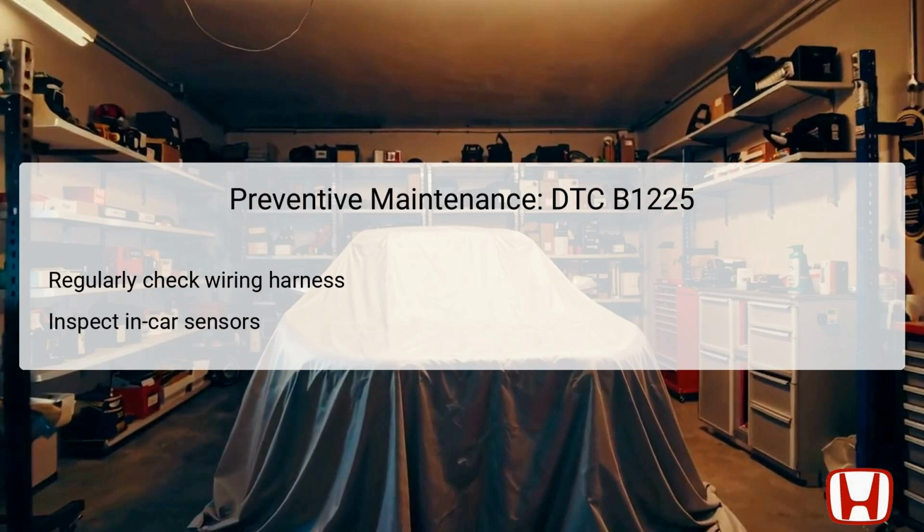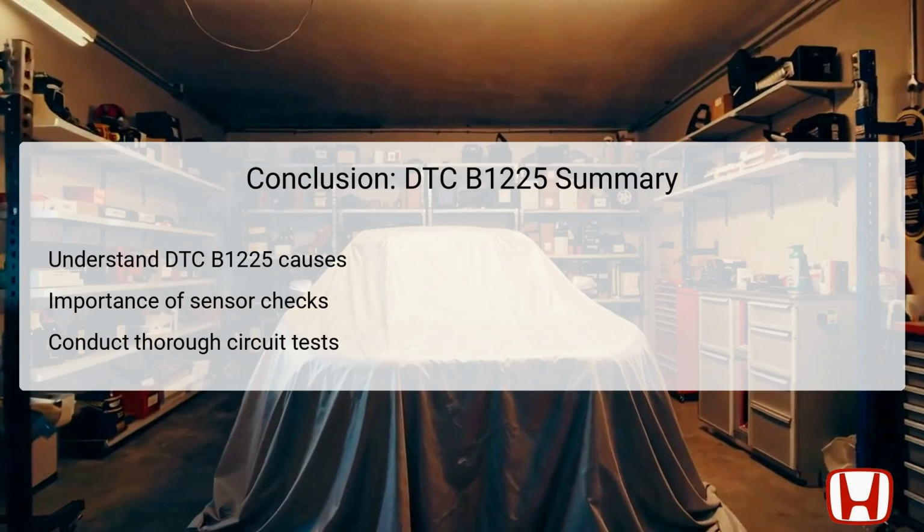Keeping these components in good condition will enhance the reliability of the climate control system and ensure passenger comfort over time. This proactive approach can save vehicle owners time, money, and ensure a pleasant driving experience. In summary, DTC B1225 highlights a critical issue with the in-car temperature sensor circuit in the Honda Accord models from 2008 to 2012. Understanding the causes, such as open circuits or faulty sensors, allows technicians to effectively troubleshoot the problem.